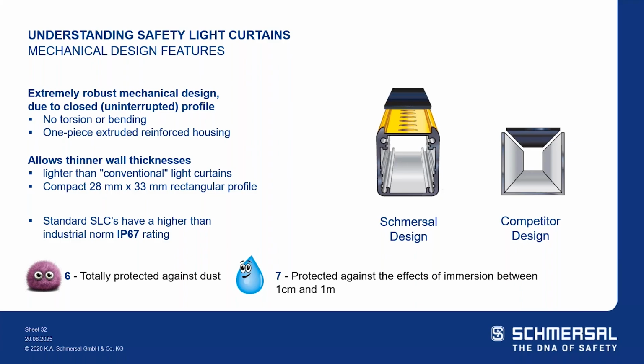Our standard light curtains also have a higher than industrial norm protection rating of IP67, where you're totally protected against dust and you're totally protected against the effects of immersion between a centimeter and a meter of water.